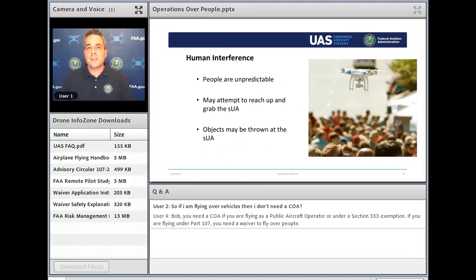So finally, the actual weight of your unmanned aircraft, and that includes perhaps any cargo or camera mounts on the bottom, will affect the injury potential. And certainly if we're flying at higher altitudes above people, the velocity of the unmanned aircraft when it comes out of the sky for a mechanical reason will increase versus flying at a lower altitude. So that will also affect injury potential.